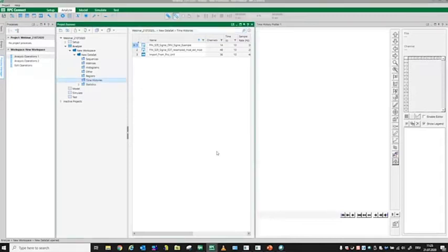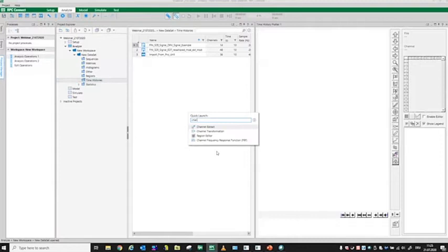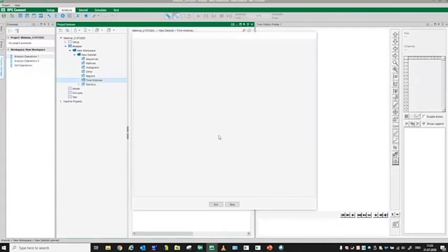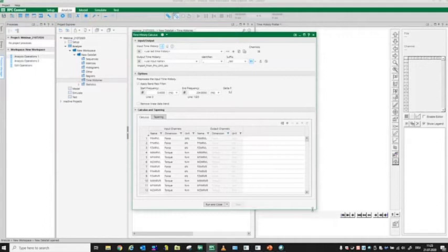Another thing which this brings along is the unit awareness. For example, let's say we go for the time history, let's say calculus, for instance. We have, I hope, some math users online. This is a benefit for math users. So let's grab any time history we have here. If it makes sense or not, let's put it aside. But now you have the possibility to calculate with this little button displacement, velocity, and accelerations for each channel. So once I hit this button, RPC will add to all length channels the velocity and acceleration.